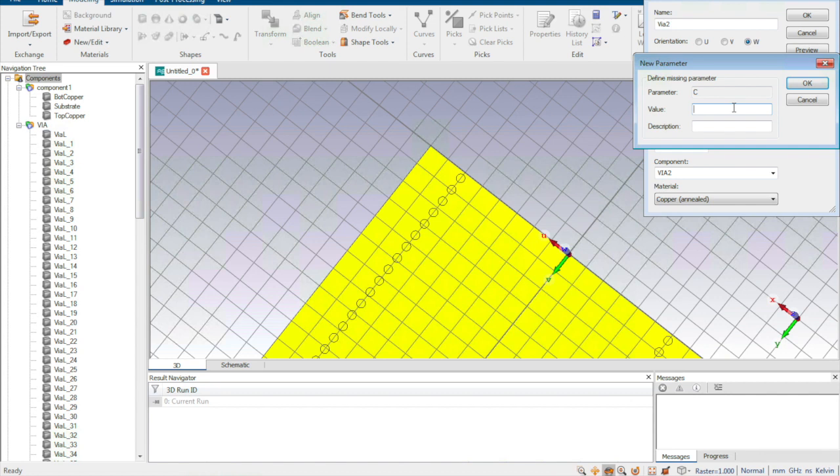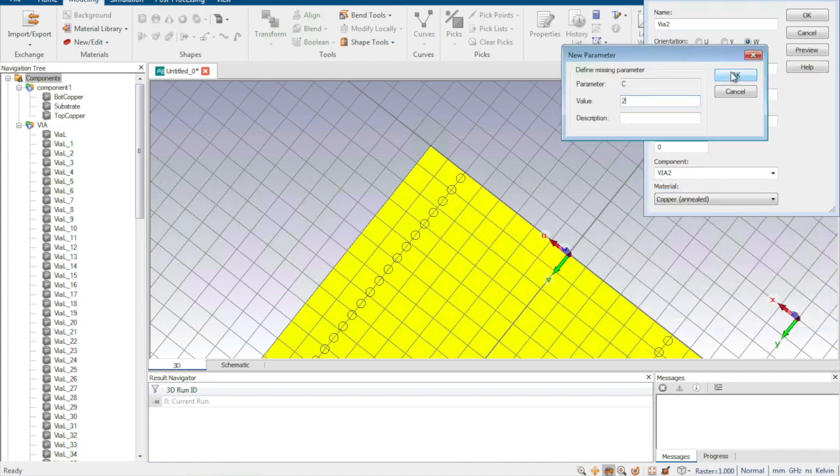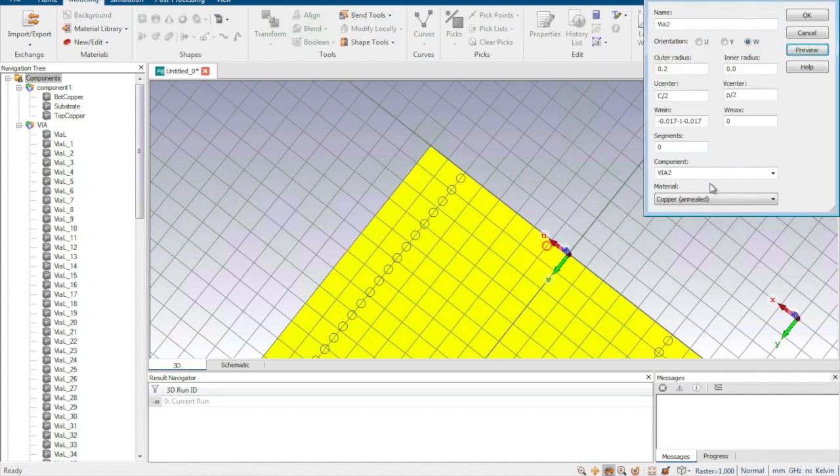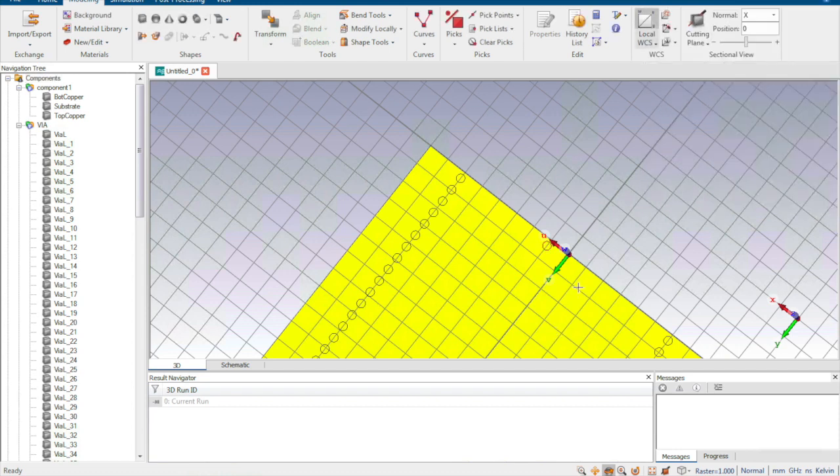Okay, preview. Let's just set C to be 2, so that we want to short this open end, but we do not want to 100% short it, since otherwise the signal cannot get into the waveguide or the resonator. We need a small slot without vias, so the EM wave can get into the resonator from this little slot. Okay, it looks good.